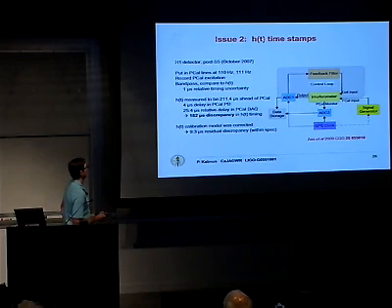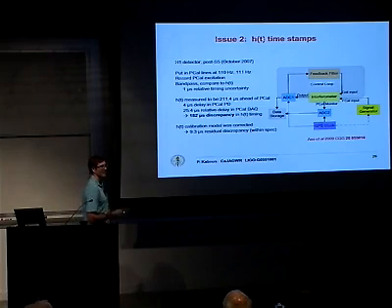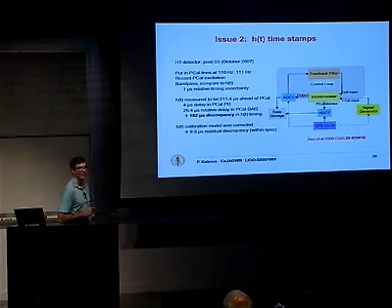So if we account for the photodetector and the photon calibrator box, and we account for the data acquisition, we can figure that out. And we looked at the timestamps on the H of t and the timestamps with these corrections, and we found out that there are 182 microseconds between those timestamps on those bits that we didn't know where that was coming from.